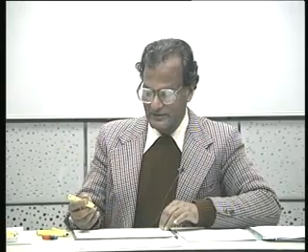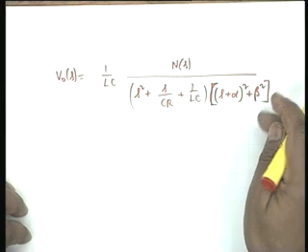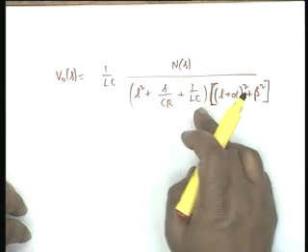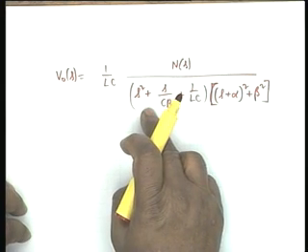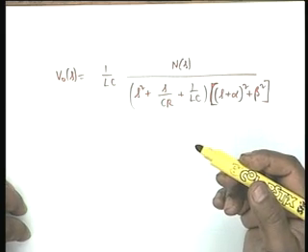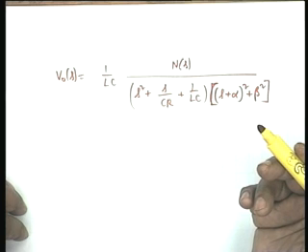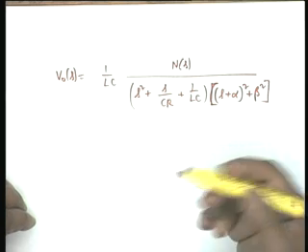Okay. Now, possible location: these represent poles of the excitation, and these represent the natural frequencies of the network. Now, depending on the values of R, L and C, the poles can be on the negative real axis, or can be coincident on the negative real axis, or can be complex.